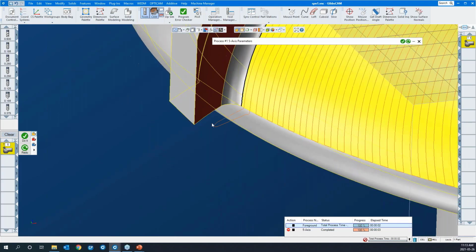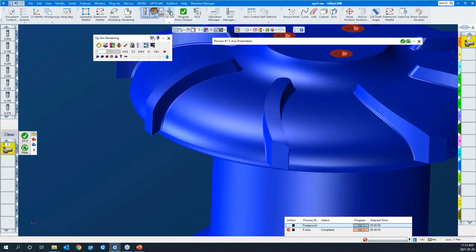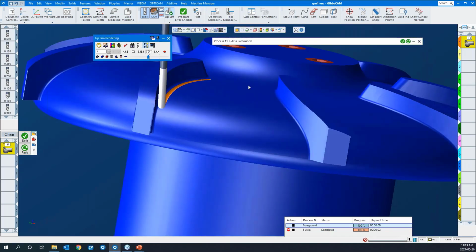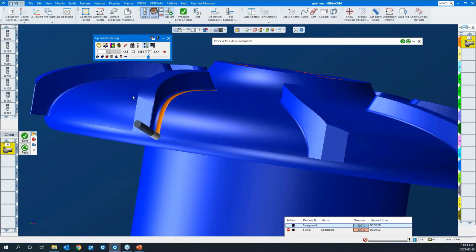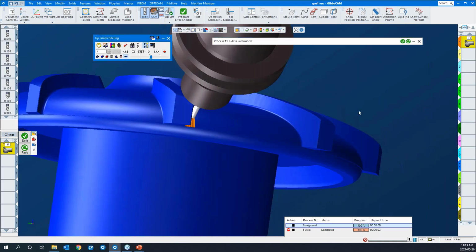And you can see there's a little jog in the toolpath, and let's look at the simulation. See how that behaves. I'll slow it down a little bit, hit play. So it comes down and you can see the tool is actually missing there. While it's running simulation, you can single block it at any given time. You can put the tool holder on there as well.